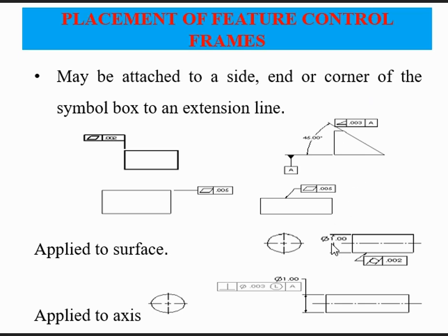Similarly, let's talk about this object, this symbol. This symbol is for cylindricity, right? This is a shaft which is supposed to be cylindrical, whose diameter is 1 mm. That is what the drawing is saying. But let's say I want to manufacture hundreds of shafts with a diameter of 1 mm. Again, it's not possible to maintain the cylindricity, which is one of the aspects of round objects.